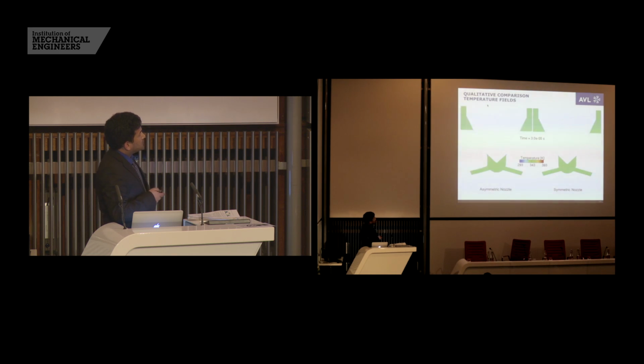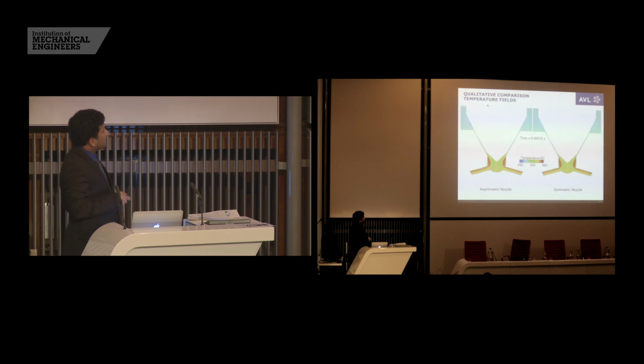And now the temperature. You can see here there are really heating zones due to the flow. There is a gradient of temperature in the flow field. When it proceeds, you can see this during the needle lift. You can see these regions due to the shearing term from the enthalpy equation.